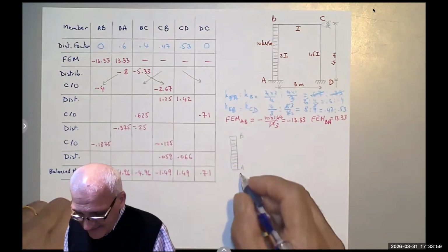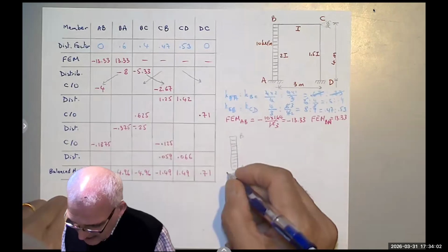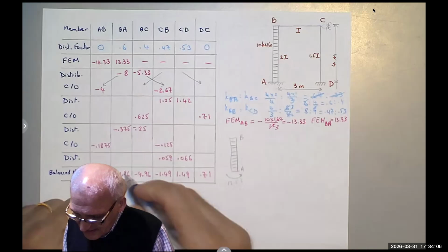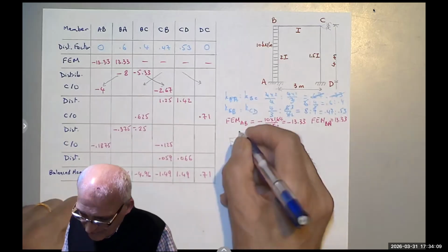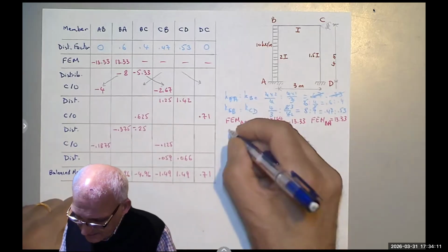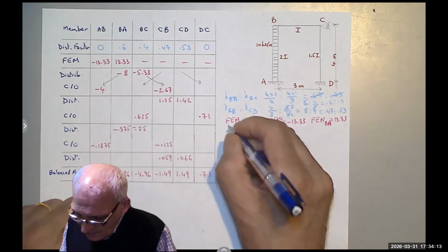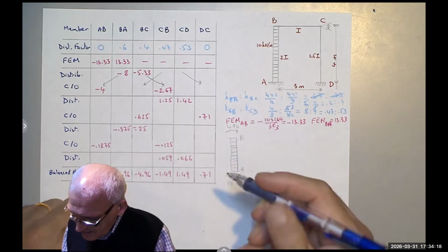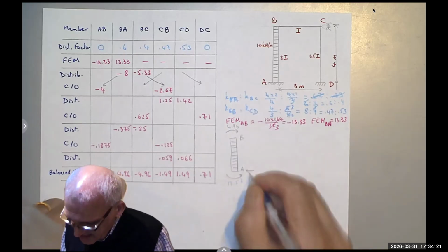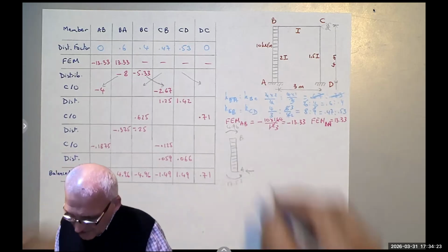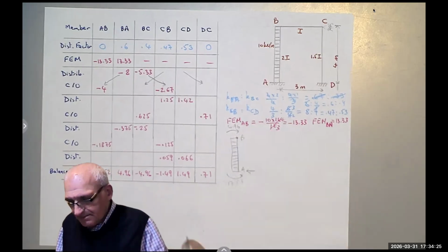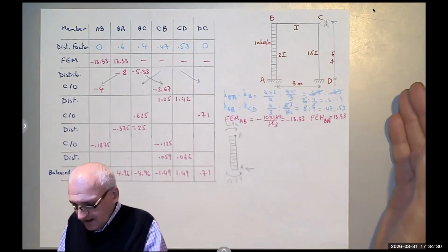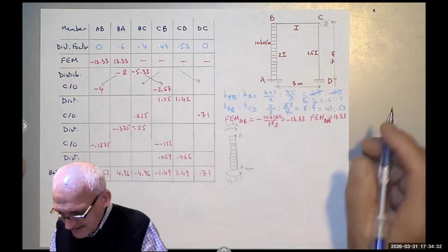The moment at A is negative, meaning it's going counterclockwise, 17.52. But the one at B is positive, meaning it's going clockwise, right? 4.96. And I have an AX here. So I'm going to take the moment about B. This one is going clockwise, so I'm going to move it to the other side. I'm going to calculate the clockwise as positive.